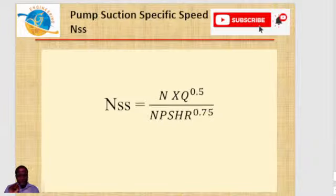Like I said, the pump specific speed, which is your NS, is an indicator of the impeller geometry and discharge characteristics, an indicator of the impeller shape. All right, while the pump suction specific speed is an indicator of the impeller inlet geometry and suction characteristics. The pump suction specific speed tells you how aggressive your pump suction condition is.